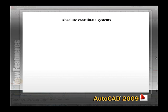In school days, you might have been familiar with drawing on a graph sheet. Likewise, working with AutoCAD software is also similar to working with a graph. The standard way of feeding coordinates to AutoCAD is by typing them into the command line and pressing Enter.